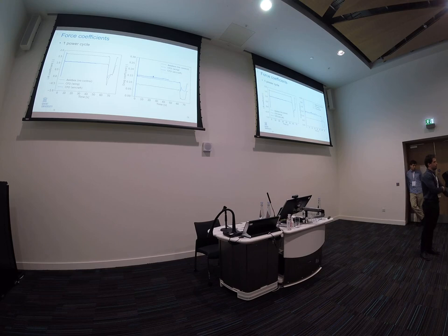And that's even with a coarse mesh. It's indeed even with a coarse mesh, because for the wing we use wall functions, so we could go much finer there. But again, there's still a lot of room for improvement. I actually have a rather big background grid. Also, the mesh of my tail is quite fine, it's actually a similar mesh to my wing. So I could do a lot of optimization there. For example, if you really want to focus on the wing aerodynamics, maybe refine a bit there and then be a bit coarser elsewhere, where we are less interested in results or where it's less critical. So there's a lot of room for improvement also in the mesh itself.